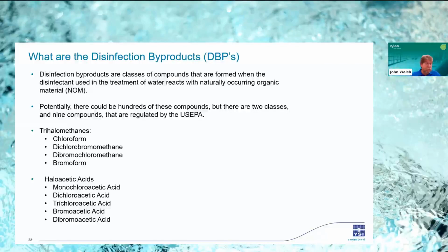In the presence of chlorine, which will be in the form of hypochlorous acid, hypobromous acid is also formed. Hypobromous acid is nearly 100 times more reactive than hypochlorous acid. So hence, a small amount of bromide in water can result in the formation of the brominated byproducts.